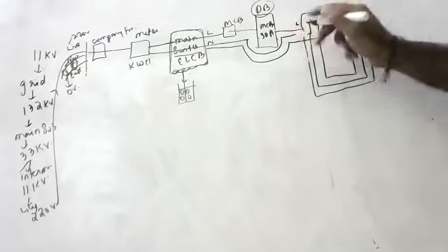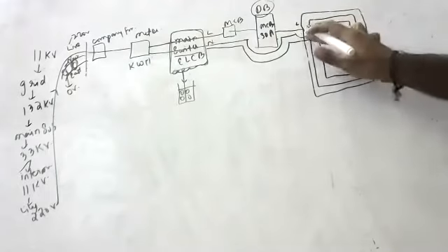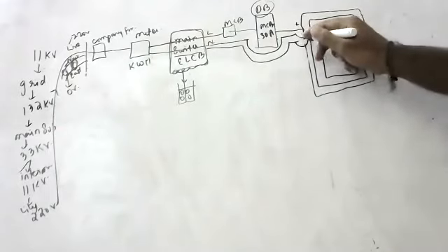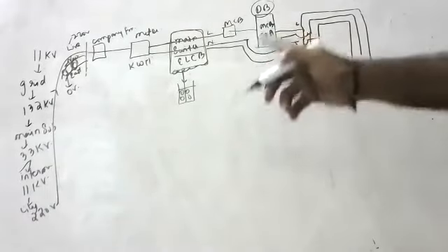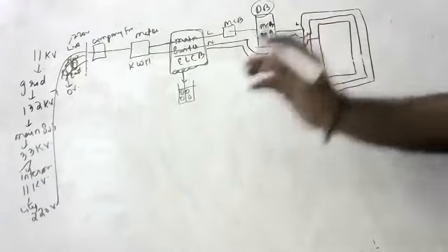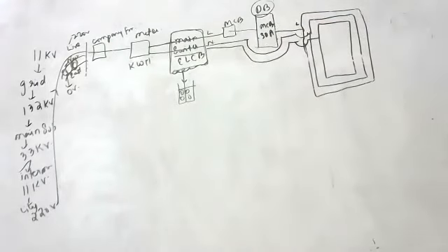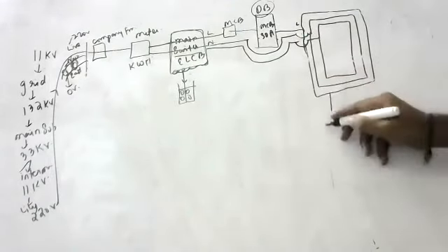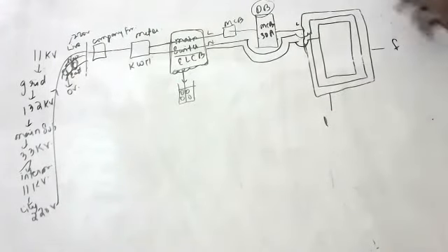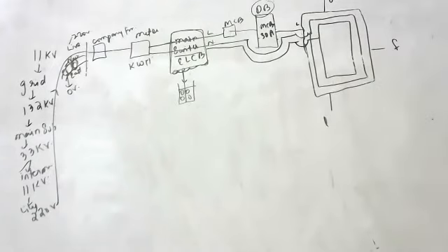Here I will put it like this, children. If I put it like this, it is not touching. This is the initial picture. So the distribution box has an MCB of 30 amperes for each ring circuit. A separate connection is taken for each appliance from this live wire. Suppose one for a lamp, one for a fan, one for a plug socket. Wherever you want, you will take a connection, children. Now how they will connect, I will show you.